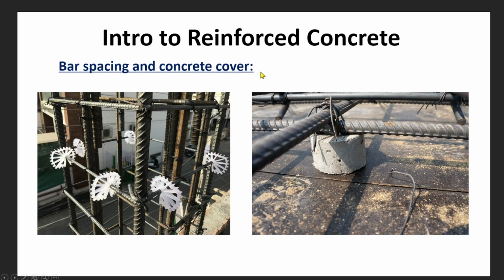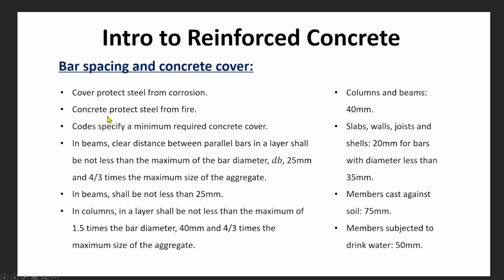Bar spacing and concrete cover. We have these covers or spacers. The cover is defined as the spacing between the formwork up to the outer edge of reinforcement, and this is very crucial in the design and the practical field. There are some plastic spacers, and there are some specimens of 2.5 centimeters.